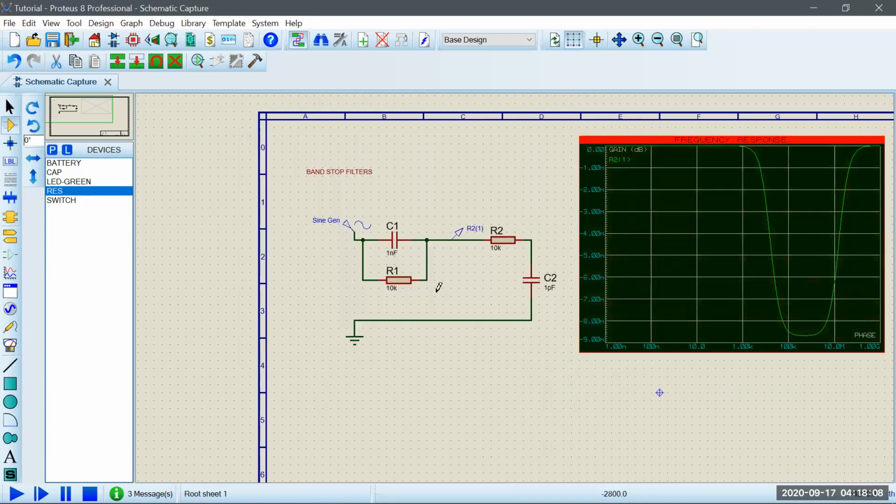So in this graph, we can see that a specific frequency is attenuated. It's somewhere around 100K to close to 10 megahertz. So here it's accepted, meaning it's similar to the input, but in a certain frequency, it is closed, and in another certain frequency it is open.